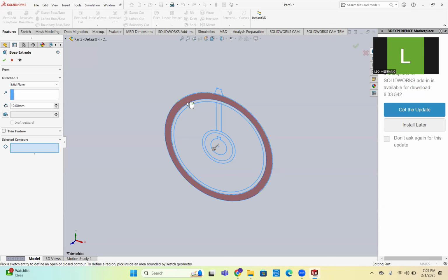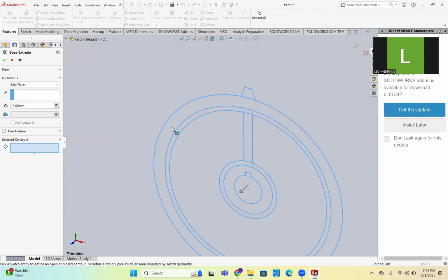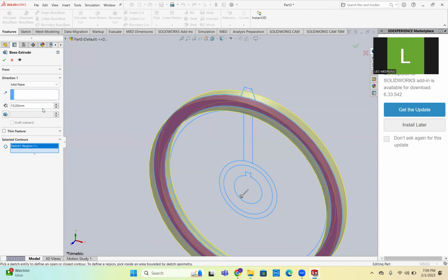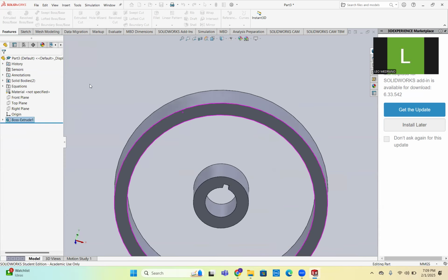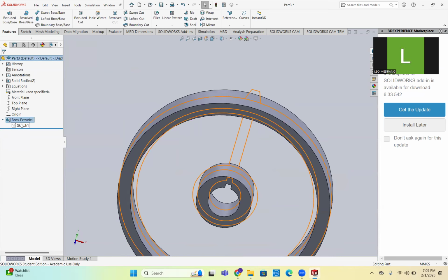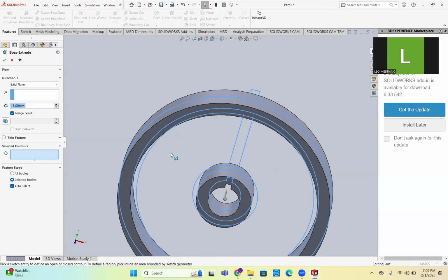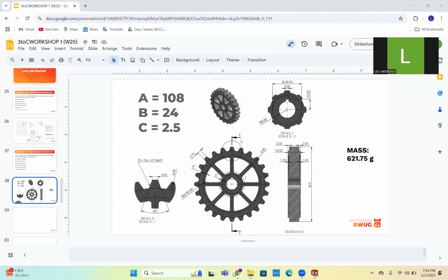But what you notice is you can click the lines or you can click in between. If you click in between, it'll highlight red. Awesome. I should also change this to 18. Awesome. We're good. And then I'm going to do this one, 18. Awesome. Now that that's done, this part is cool. Hit on your feature tree the drop-down arrow, hit the sketch, hit extrude boss base. Now, what we're going to do, if you look at this, is do the pillar, the circles on the pillar.